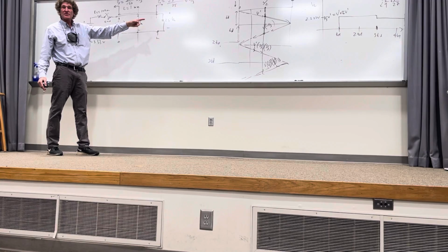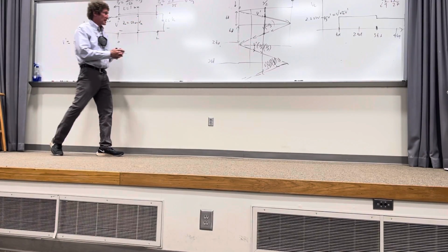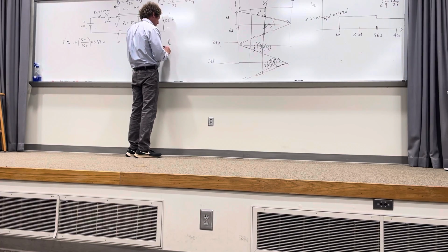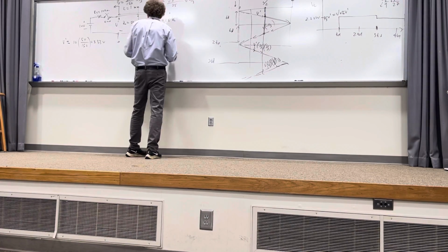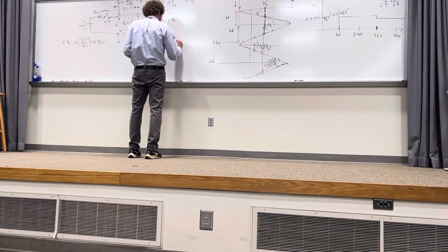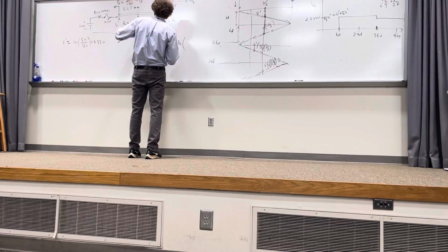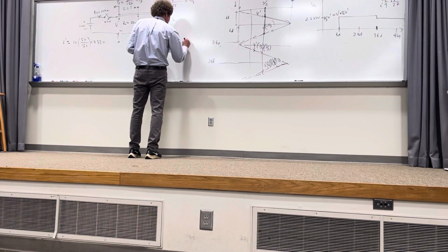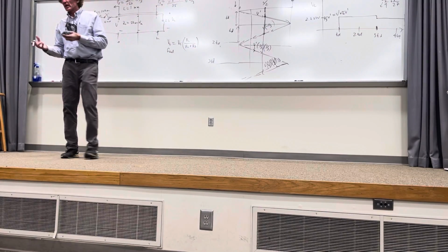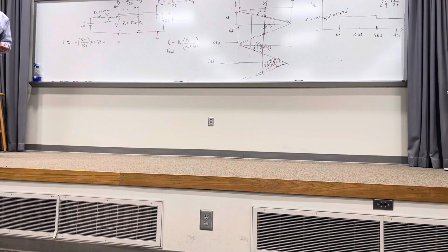And therefore, the final voltage at the load, called V load final, will just be equal to voltage V source, and then you use voltage division, but Z0 has nothing to do with it. It's just RL over RL plus R source. Are you with me? So it looks like the transmission line isn't even there as t goes to infinity. All the voltage at the load is dictated by its value and the source resistance, and of course the 10 volts or the source current. Okay? Everybody see that? Keep that in mind.